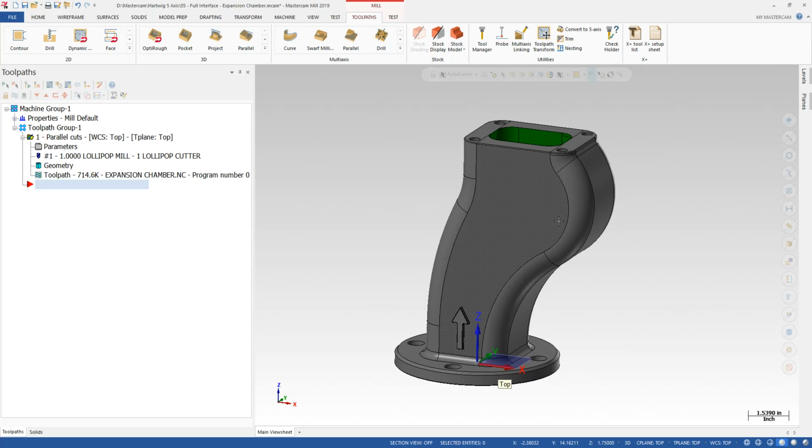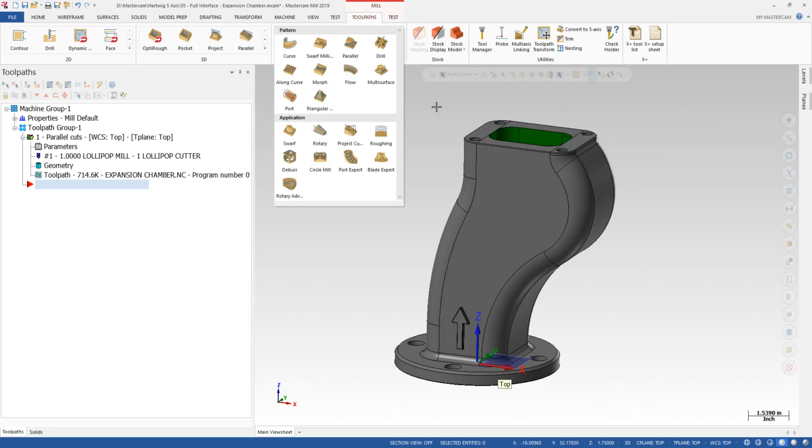It gets a little more involved when you're talking about a 3D or a 5-axis toolpath, in the sense of, well, I want to start at the top and blanket down or quilt down the side of the part, or morph down the side of the part. Maybe I want to slice my part up in Z and then just contour around it and step down in even sizes, even step downs. Mastercam has a series of toolpaths to be able to do this.